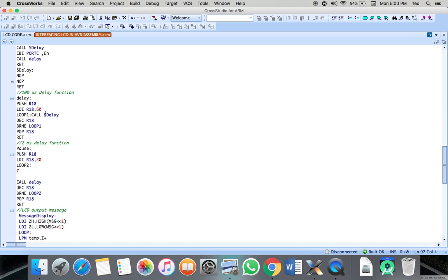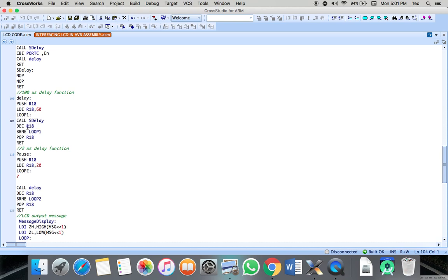So under the delay section you push the contents of your R18. Then after you do that, you load 60 into your R18. Then you call your loop 1. So under loop 1 you call your delay. You decrement the contents of R18. You keep on decrementing until it gets 0. If it's not equal to 0, you branch again back to loop 1. If it's equal to 0, you proceed with the operation, pop R18, then you call the function return so that you continue from where you jumped before you called the label delay.